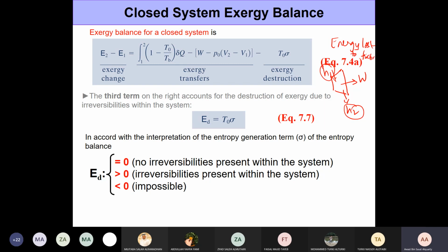But from an exergy perspective, the exergy that we had at state one, which would represent the maximum work that you could extract, is partly destroyed as it goes through the expansion process. Because the work that you get in an actual turbine is less than the work that you would get in a reversible process. That's simply because some part of the potential to do work is destroyed, because it's lost in overcoming undesirable effects such as friction and other irreversibilities.